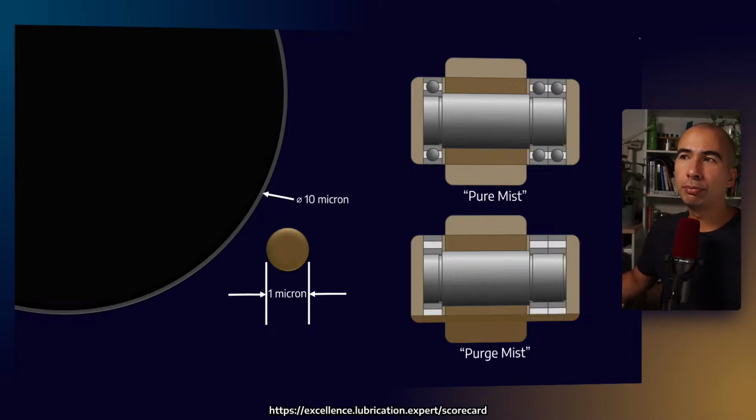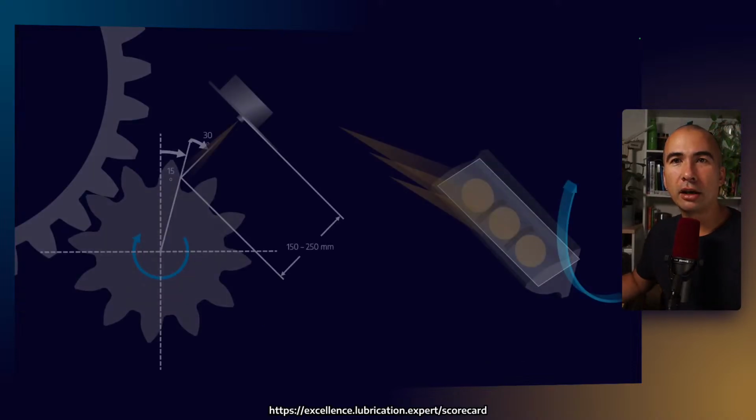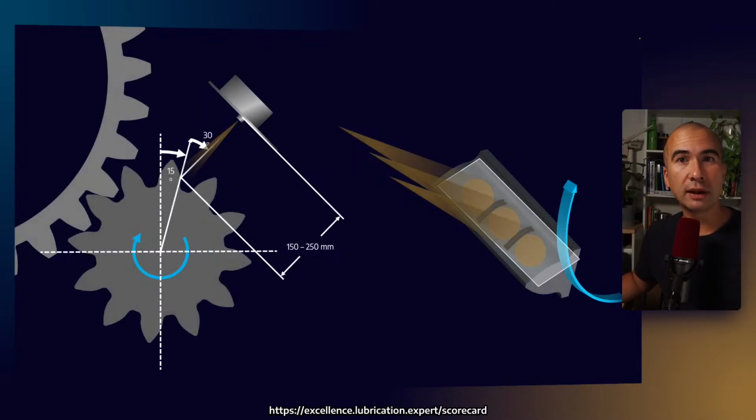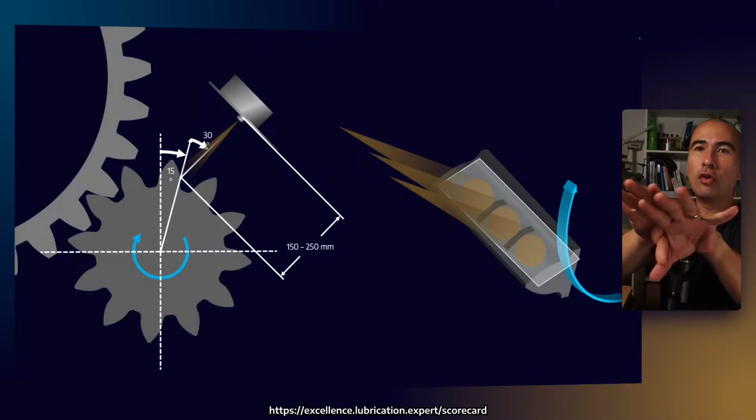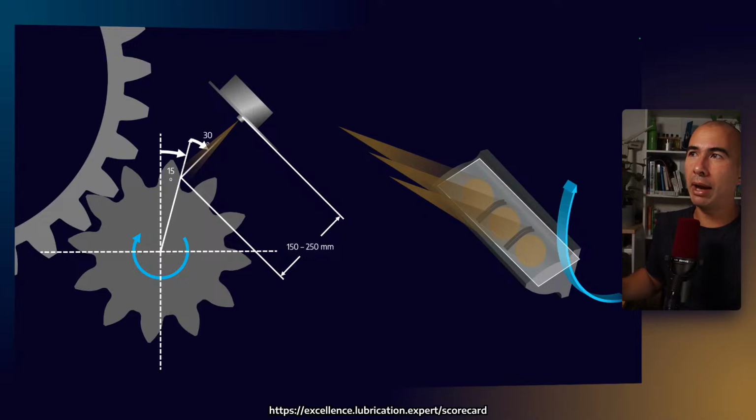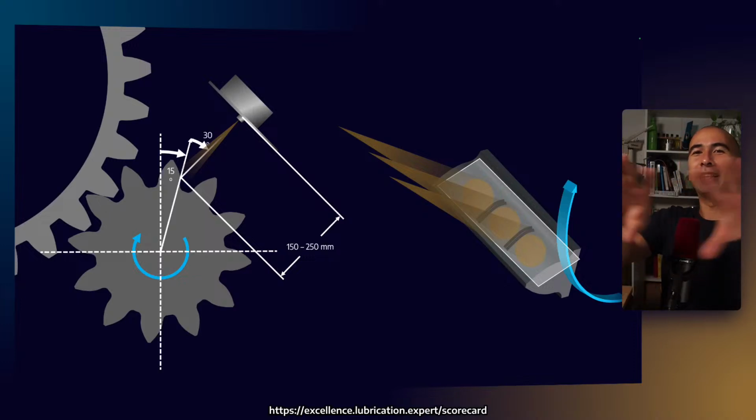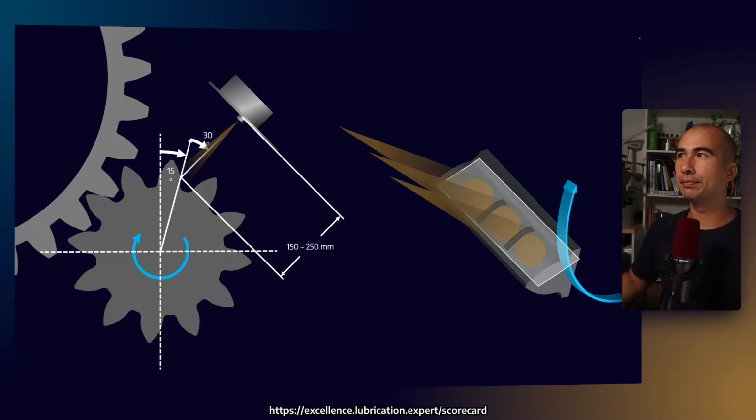When we are spraying any kind of lubricant, for example, in an open gear setting, we want to make sure that there is overlap over the spray patterns. So a general way of ensuring that you've got overlap is just to put a piece of paper in front of the spray system and see that there's overlap in the spray pattern.